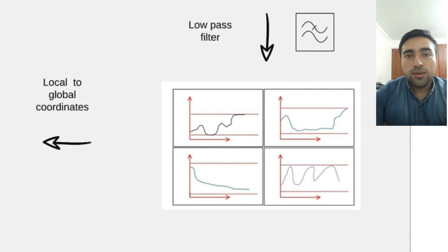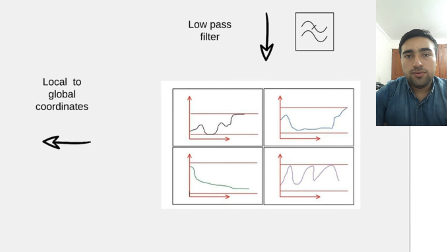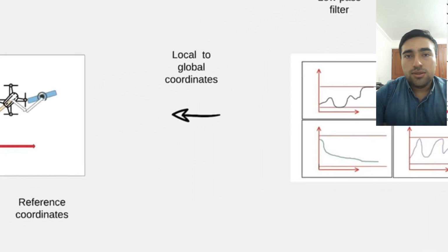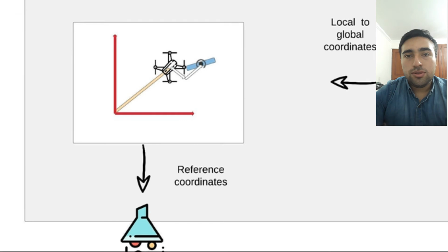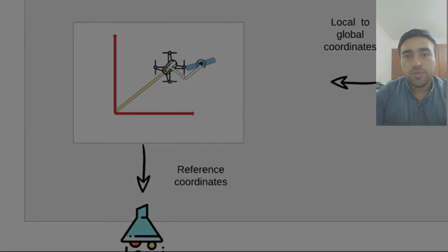The vector of movement tells the drone how to move. However, it is set on the local coordinate frame of the drone, while the control system uses a global set of coordinates. A transformation needs to be made in order to make these two signals compatible. This is done by adding the position of the drone to the vector of movement. This results in a signal that the drone will follow in order to complete its path.